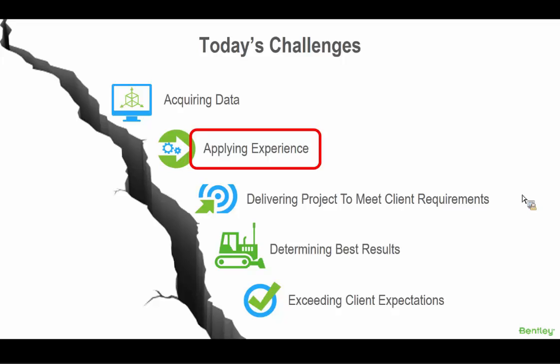I remember when I had a company, one of the things I used to tell employees, for clients, if we can get within about 3 to 5% accuracy on cut versus fill, that was pretty much about as good as we're going to get, because going that extra mile to get it perfect usually took too much time and cost too much money for my company to stay competitive. So a lot of times we didn't do it unless you could just really see it.